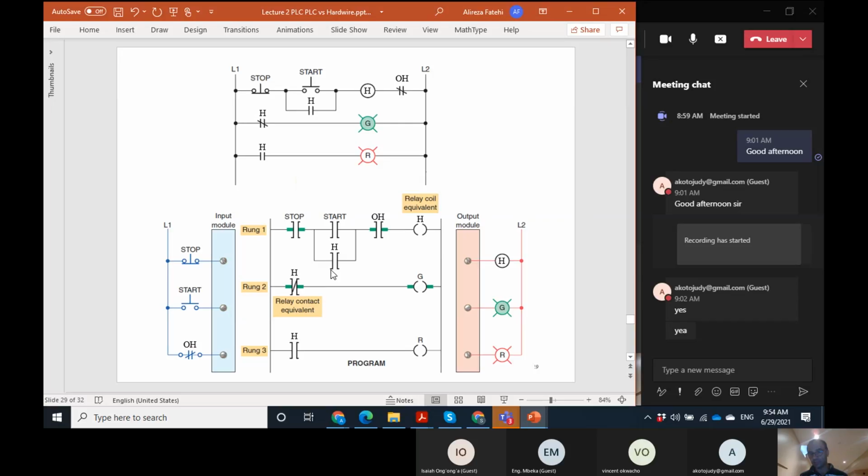Regarding the auxiliary contact, this is also very important. Why do we need these auxiliary contacts? To keep the command. In fact, this is a push button. A push button is a button that is connected momentarily. You just push it for a short time and release it, and there's a spring on it that releases it. So this is closed just for a short time, momentarily, but we want to keep the command. So we need to do that.